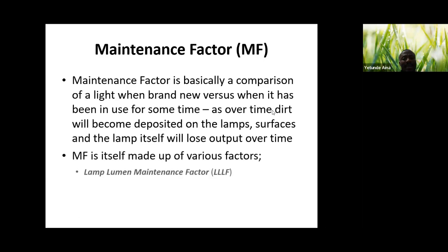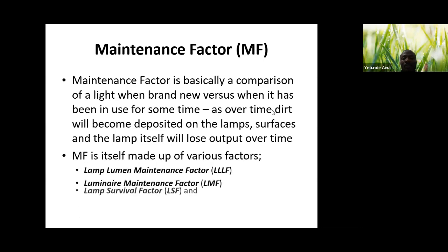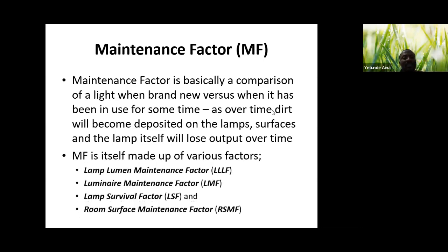And looking at this MF itself, it is made up of various factors such as the lamp lumen maintenance factor LLMF. Then we have the luminaire maintenance factor LMF, the lamp survival factor LSF, and the room surface maintenance factor RSMF.